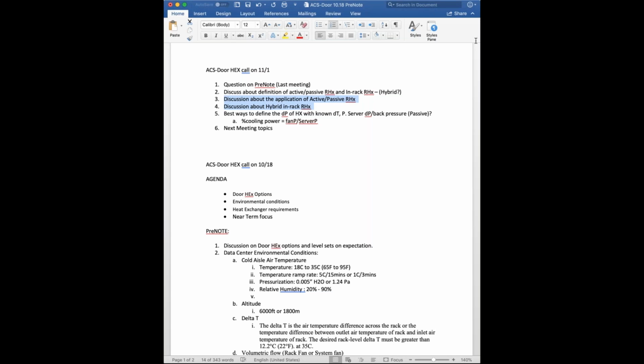say 0.3, right? And say that 70% of the heat is being dealt with by a cold plate or a direct-to-chip technology. That means that, to make the economics work, you need a rack that's at about 30 kilowatts of total load. So in my view, and based on my pretty extensive experience with this application and this approach, I'd say that you really have to go to a hybrid approach with compacted racks to have it make sense.